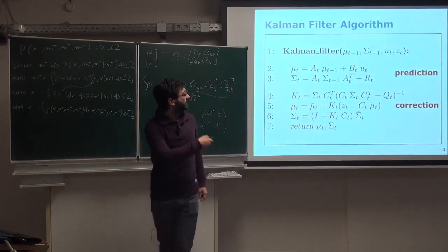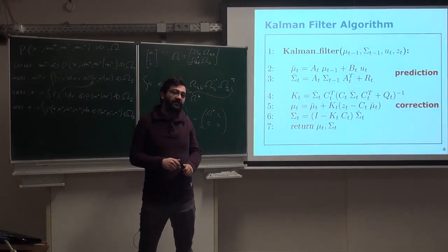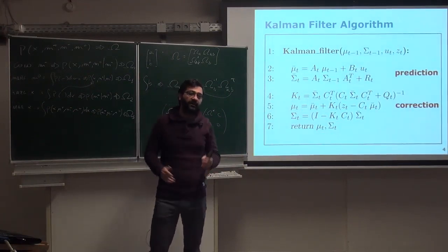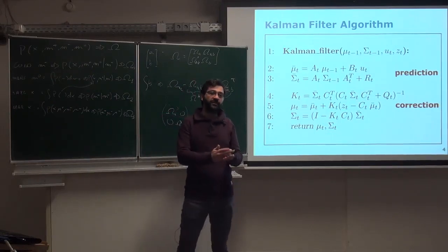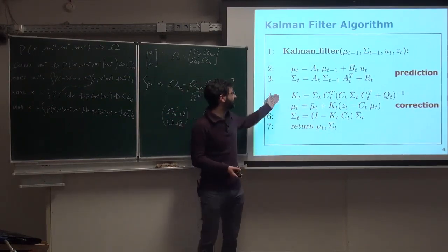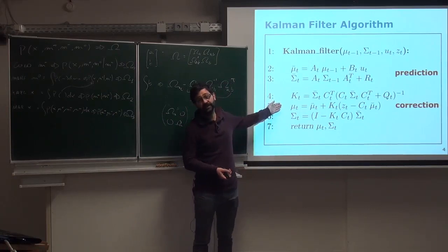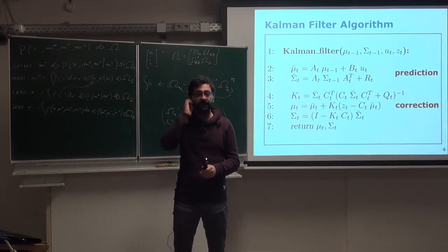This is the Kalman filter, and the beauty of it is that on one side it's optimal if you can meet the assumptions: linear system, linear observation, and Gaussian random noise. And on the other side, it's just made of 5 lines of code. So that's very simple, elegant, and quite effective if you meet the assumptions.